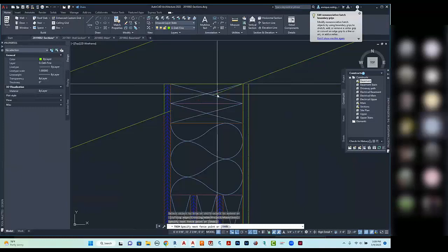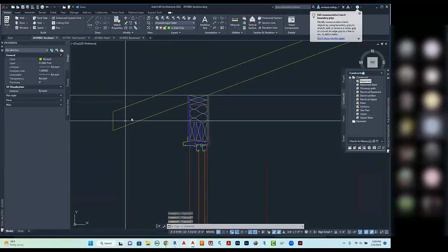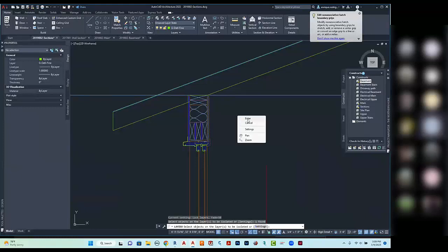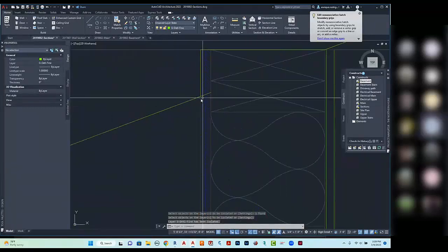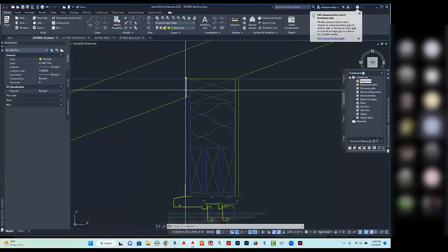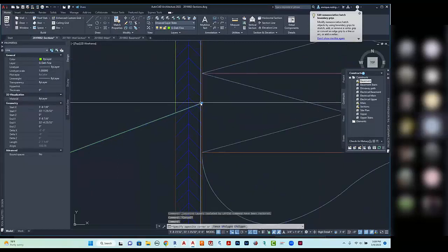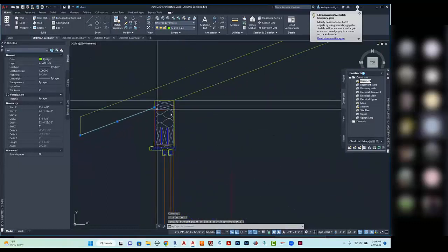And I can take all of this out here. If I was to lift this off, you would see a little bird's mouth cut in there. In fact, if I isolate the layer, you can see it right in there. So I actually have to cut this back a little bit right now still. So let's go ahead and undo. And let's take this guy. I'm just going to drag it back from here to that point.